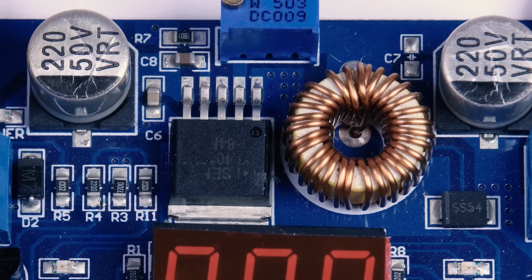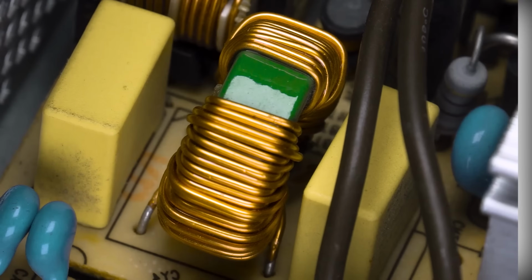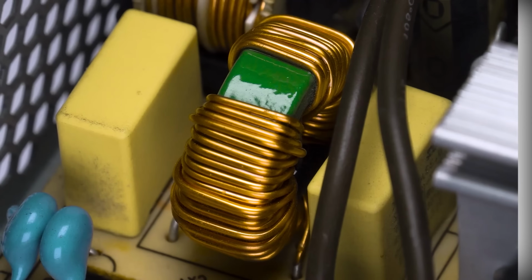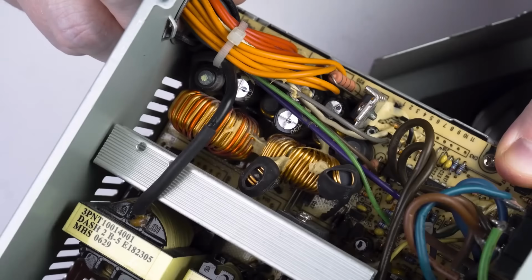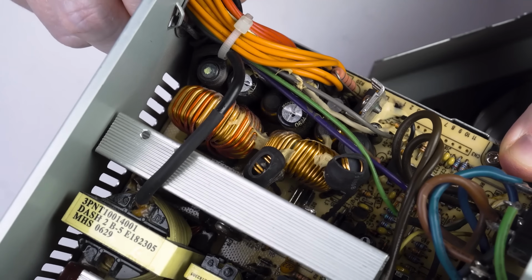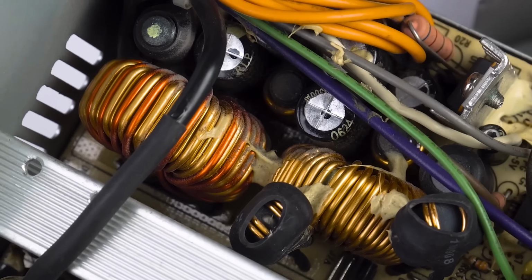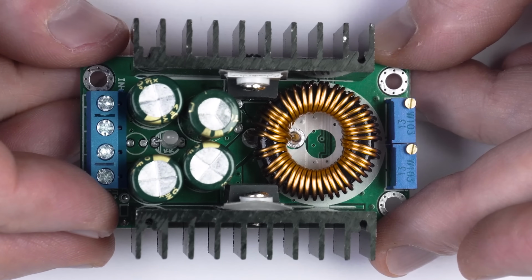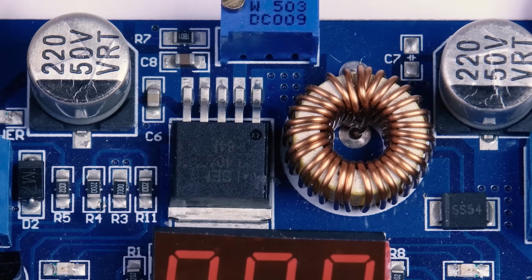Another typical function of an inductor is high-frequency noise filtering. As we have observed, the inductor absorbs the primary voltage spike that occurs when power is applied to the bulb. In a similar way, being part of a power supply, it smooths out all sorts of spikes and noises that occur during the operation of the device. Inductors nowadays are also very commonly used in step-up and step-down DC-DC converters.